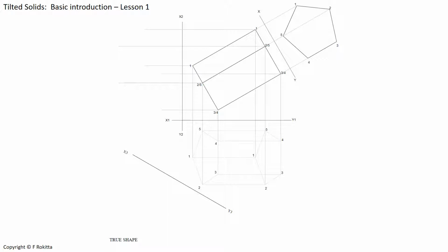We do not draw in any of the lines solid yet because we first have to establish which parts of the prism will be seen and which parts of the prism will be hidden if we were to look down onto the prism, and therefore we need to consider what we see if we were to move to the front view and look at the top lid and observe it from the top down.